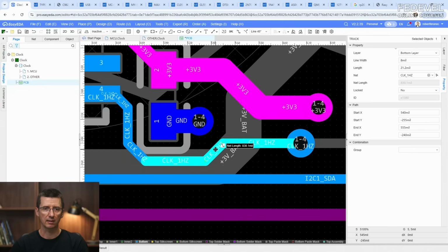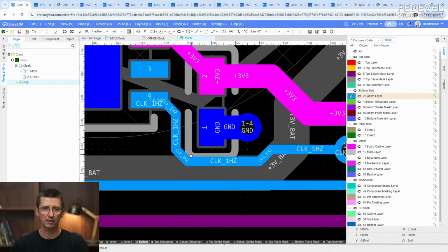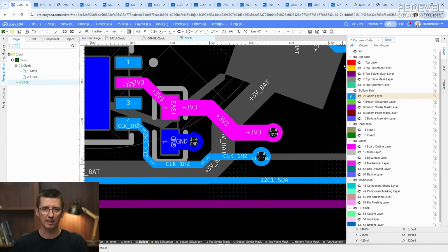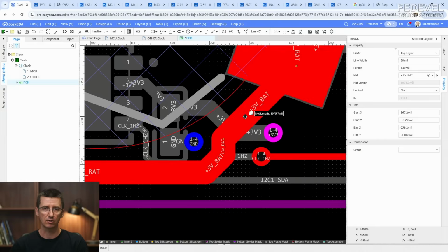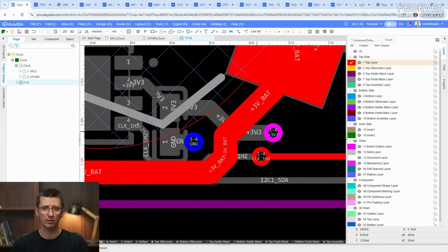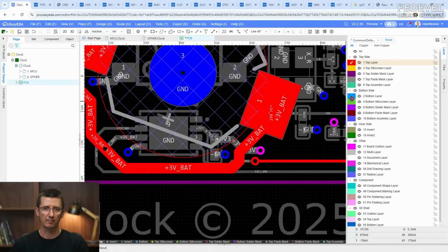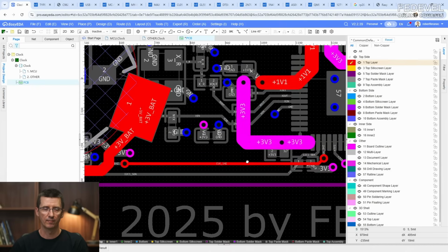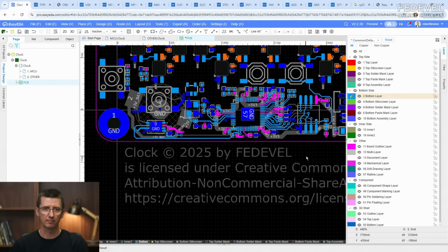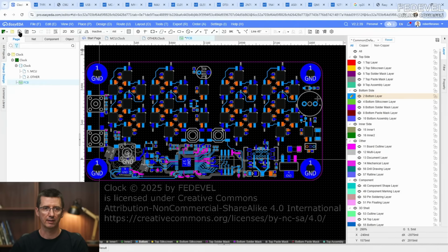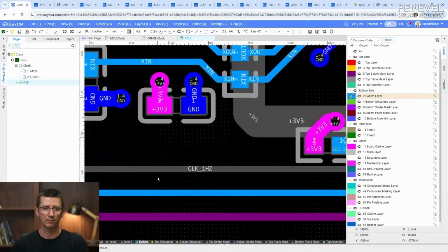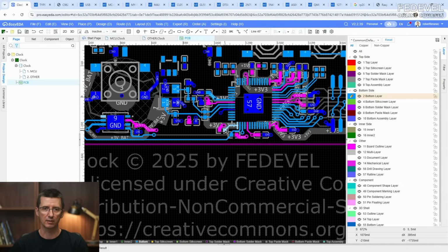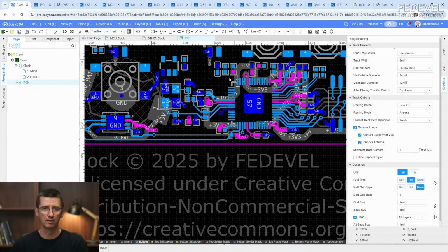Because this RTC has some kind of compensation, and it's very, very precise. If you don't use a dedicated RTC chip, you still can do some RTC clock from the microcontroller, but after some time the clock may not show the correct time, because it may shift a little bit more than if you are using a dedicated RTC chip.